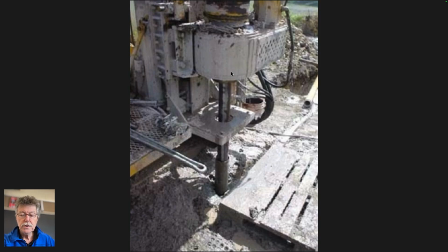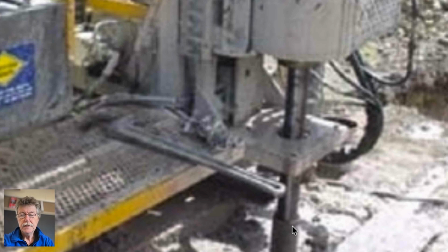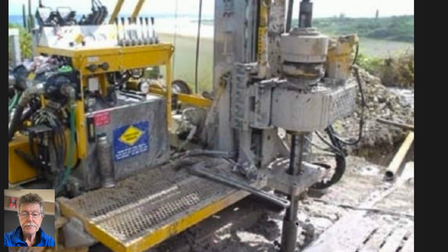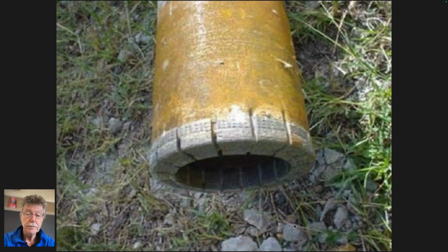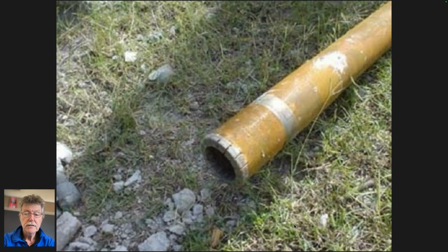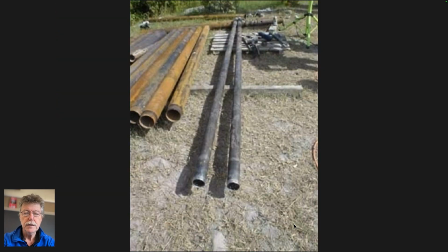The drill would go down, and once it's coupled, drilling fluid would be pumped in here, go down to the bottom of the hole, come out, and return around this casing here. So it would come out here, and I think in this case they're just wasting the material, not regathering it and putting it back down. So that's a pretty simple technique. Another close up of the same stuff. This is actually drilling with casing in this particular case, which isn't so usual.